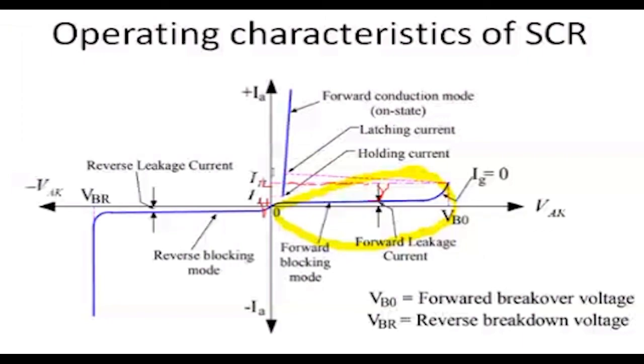There is a small mistake here: this is the latching current, and the other one is the holding current; they are reversed in the figure, so correct it. For example, after giving the gate voltage, what is blocking the current? J2. If I give the gate current, J2 will not vanish suddenly; it vanishes slowly, as if the gates are opening.